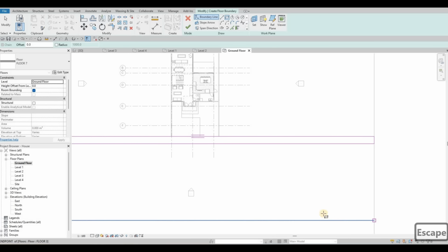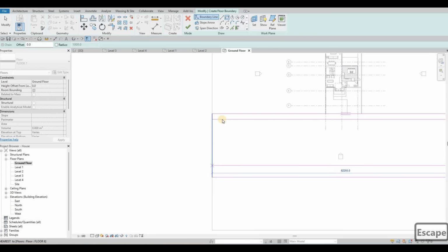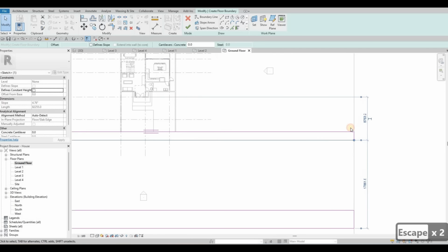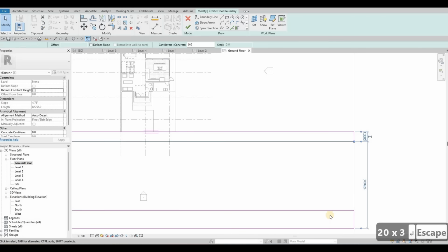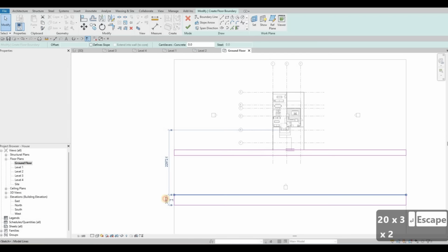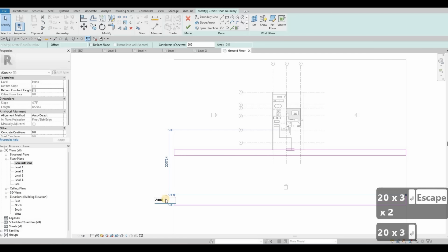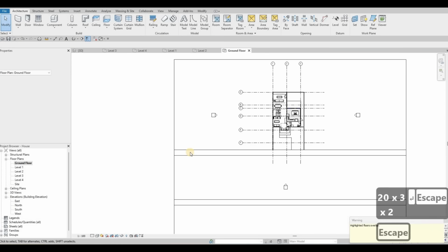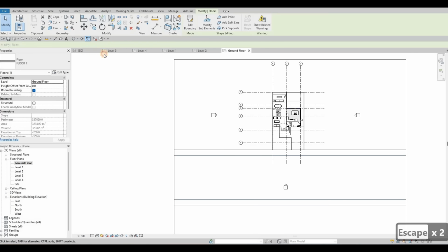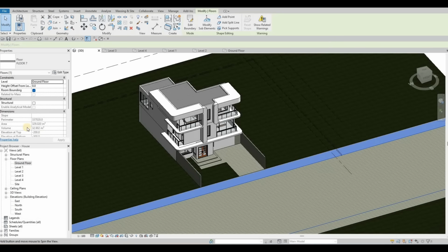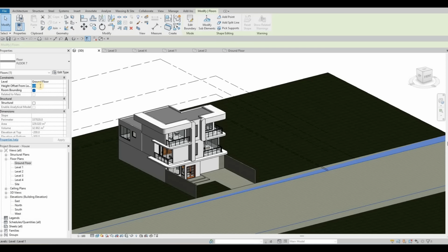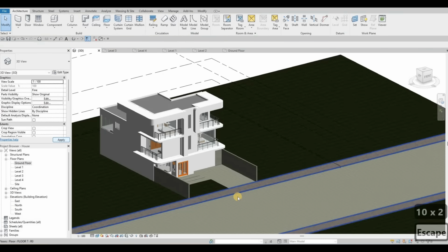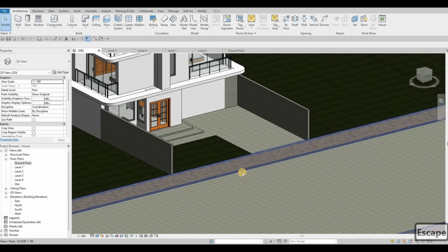And then also on this part, we want to make sure that the thickness or the width is 2000, and at the same time also here. And then click finish. It's gonna be lower here. If you see it like that, it's gonna be under, but we're going to offset this one to 100 so that it's on top of this. So now everything is good right there.